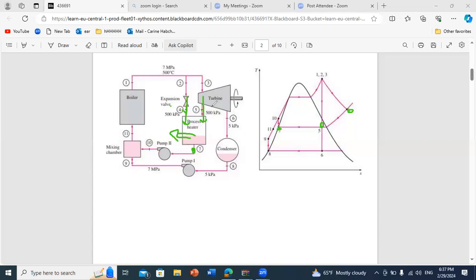And then what will happen is that different mass flow rates will circulate in the cycle. And as we said, we should annotate them to be able to answer what is the utilization factor, because now it will become more complex to assess, because it will consist of W dot net plus Q dot process.